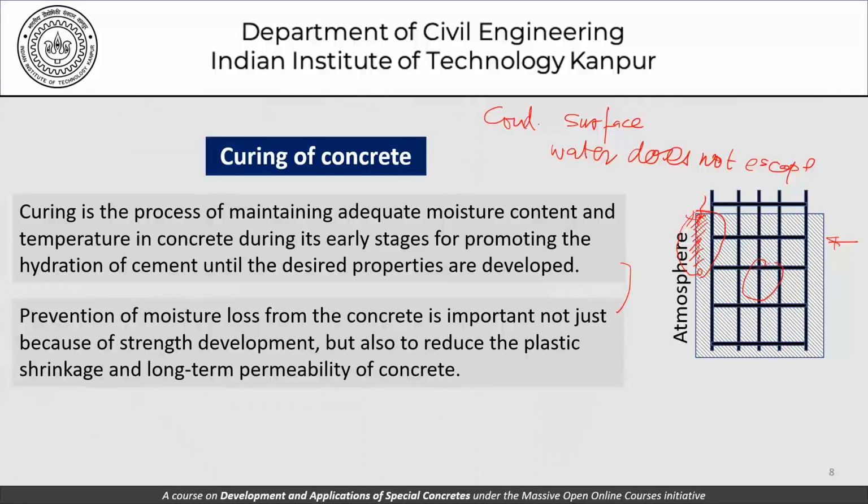Now deep inside we cannot really do much as far as promoting hydration is concerned. It's impossible to provide water. In fact, it's not even needed because in any case the amount of water that we have added is in excess of that required for complete hydration. So it's only the prevention of water escape that has to be our focus as far as curing of concrete is concerned.